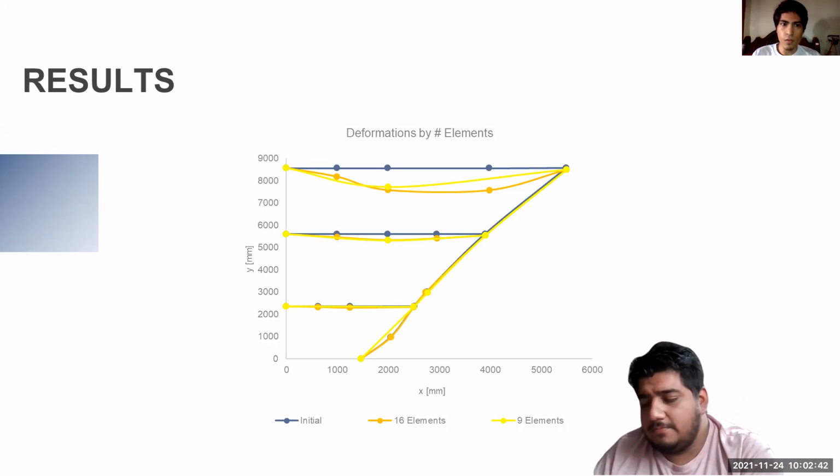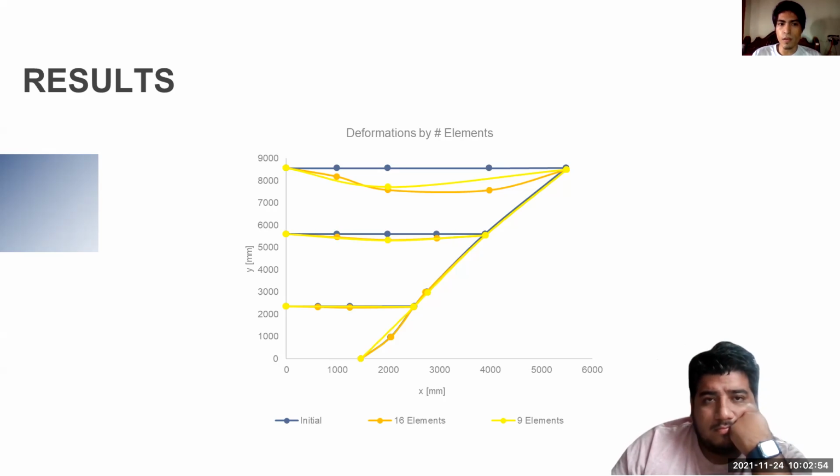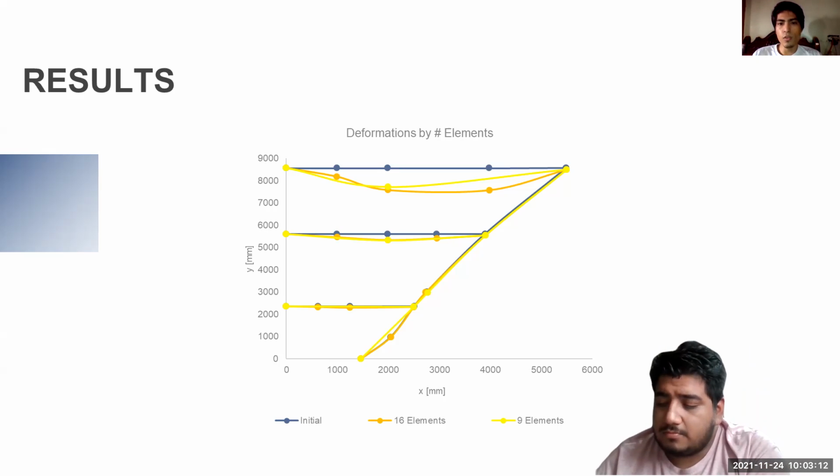Good morning. I am going to talk about the results of this project. The global deformations that we found are less than 1 millimeter, except on the upper deck. The maximum deflection is 3 millimeters because we assume the joints are not central support. Also, in order to see this deformation, we use a scale to expand the displacement of each joint.